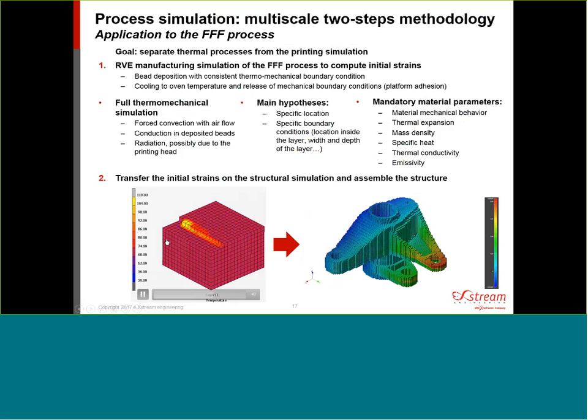Okay, so this is what we actually compute for all the representative regions of the printed parts. From this small but detailed simulation, we extract information about how material actually works, and then we can apply this layer by layer to the full structure. And this enables us to solve the printing of the part in typically less than 1.5 hours, starting from scratch. And we will see this also during the live demo a bit more how it works. So, a very efficient multi-scale methodology.